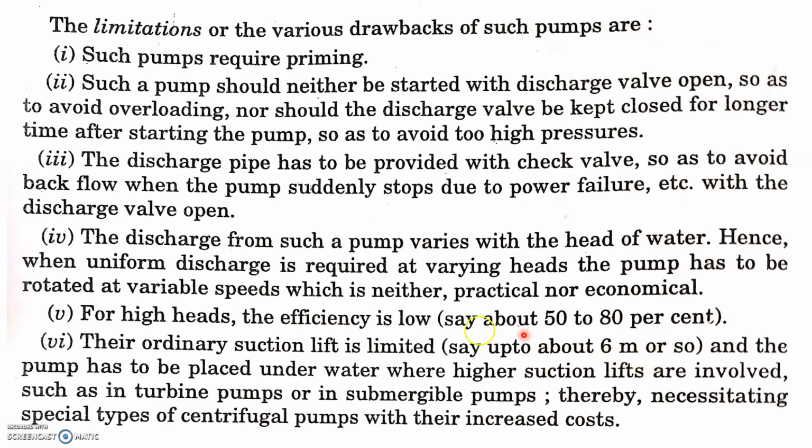If it is more than that, you need to provide different types of pump. Those are nothing but the turbine pump and the submersible pump. These are special types of centrifugal pump, and their initial cost is very high. And the discharge varies with varying head. So it is one of the major disadvantages.